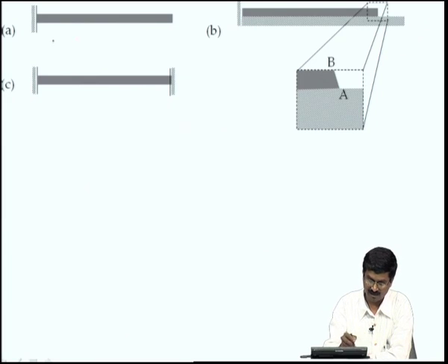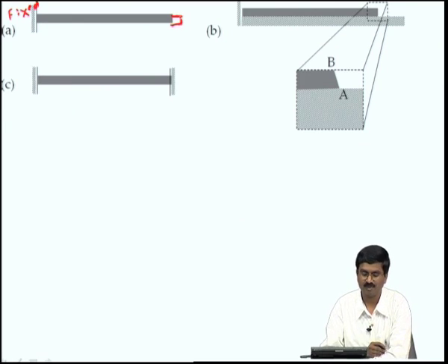Let us say I now take a beam. Previously, the interconnect we took is also a beam. So, this beam here is fixed at one end. This portion is fixed, and this portion is free. If I heat this, it will simply expand by a certain amount. So, there is nothing really interesting about this particular case. It will expand by whatever we derived in the case of the interconnect, where we said the change in length is related to alpha times the length times delta T.